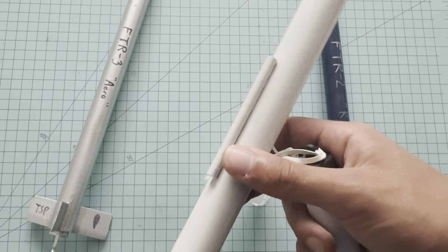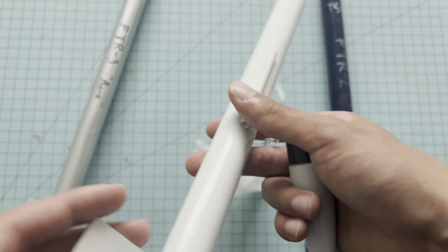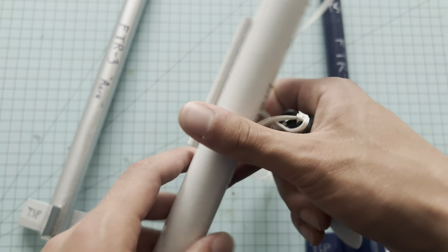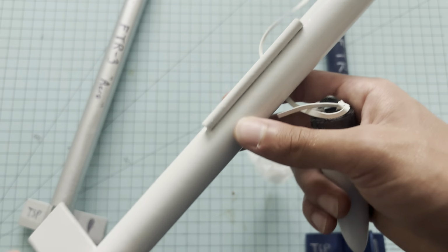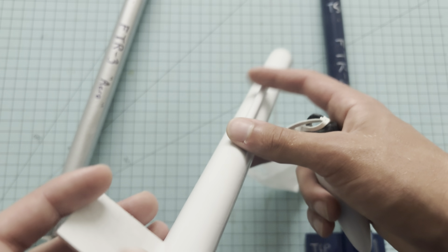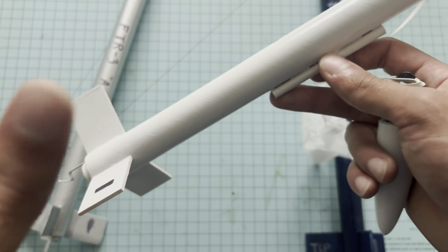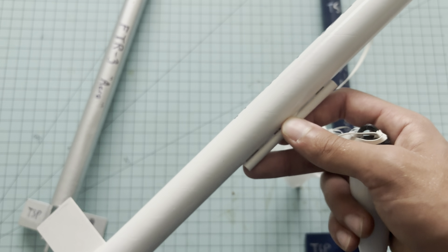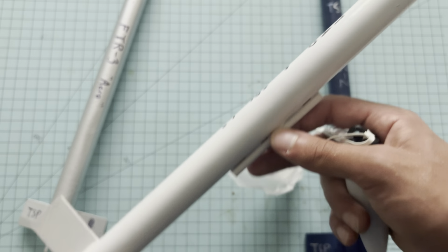And the last thing here, I just have a paper straw as a launch lug. Yeah, just a long paper straw, kind of right around the center of gravity. These ones are slightly bigger than the typical launch lug on a rocket of this size, but I just have a box of these paper straws, and I just use all of them for model rocket launch lugs. I mean, it works well. I can use a bigger launch rod, that's really never hurt anyone, if you have it.